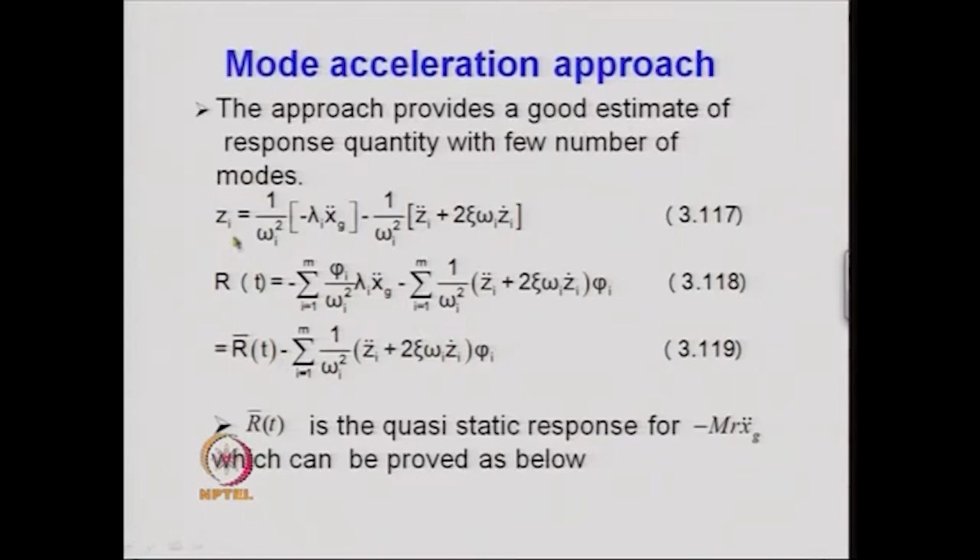Since in calculating one part of the response we have taken into consideration the contribution of all modes, this response is better than the usual mode analysis technique, because in the usual technique we consider only the first few modes for obtaining the solution.